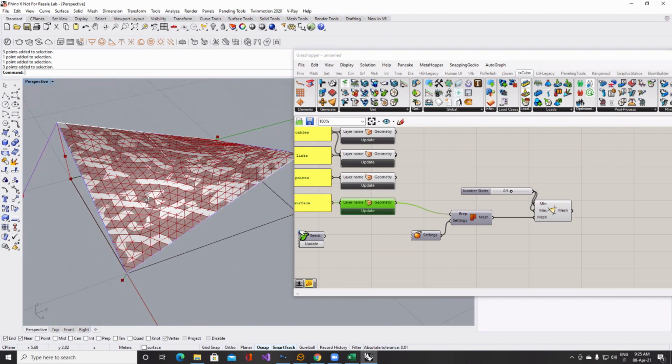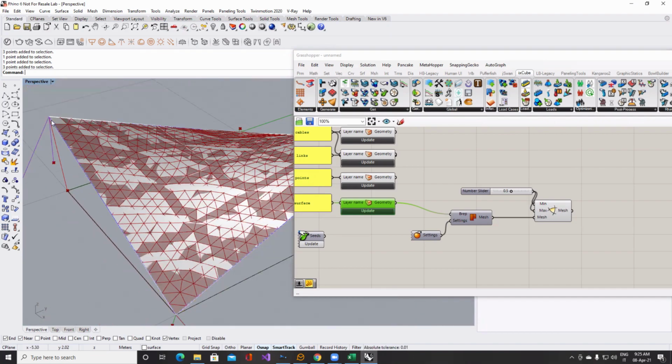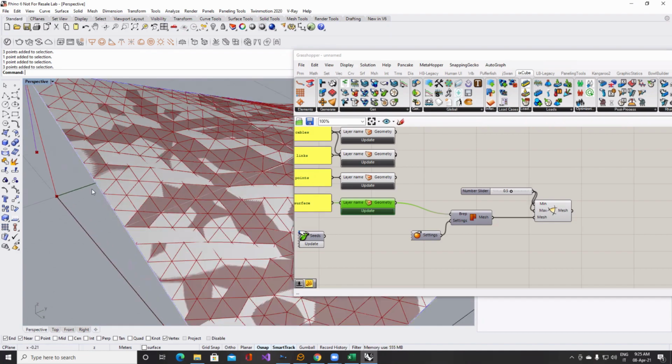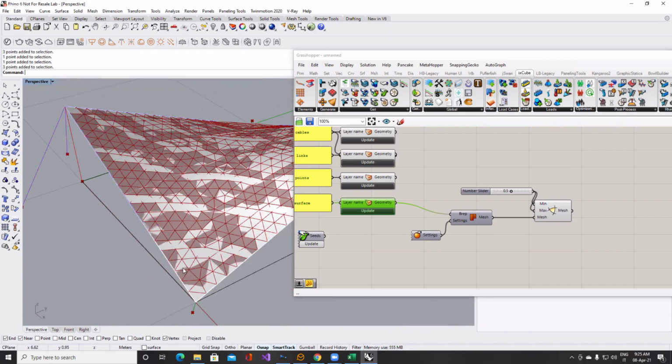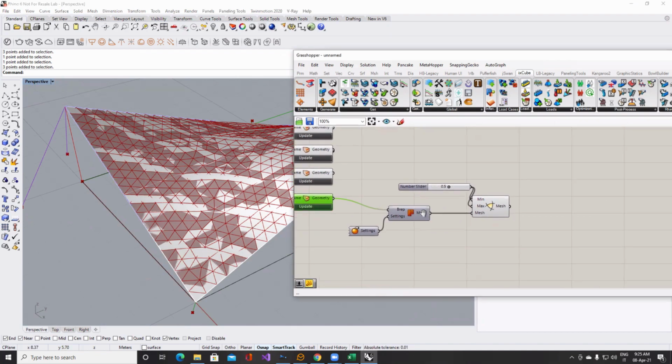Now, remember that the edges of the mesh are not just the line that I have drawn from this point to this point, but a kind of polyline. I need all these small pieces. I need a line that is split at these points. Only a line splitting at these points will get merged to the mesh. A single line from here to here will not be merged on the mesh. So clearly what I need is the boundary of this mesh. So how can we do that?